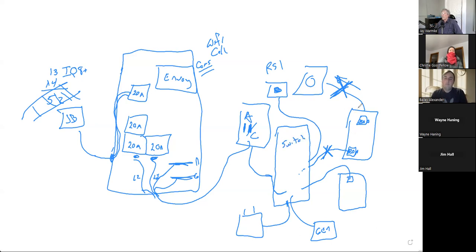All right, so it senses the grid is off and it disconnects from this service panel. Well, now everything is operating, but only to this critical load panel. We've got a generator, we've got batteries, we've got solar array. Everything is coming in, but it's only powering these critical loads.